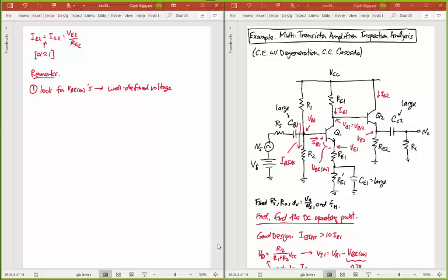And then you want to know how that VBE on, maybe added or subtracted from some other voltage, is dropping across a resistor. And then that determines your current there. So I could say right away, from both these transistor cases here, you can see that the currents are really coming from a voltage drop across RE, and that's usually what you're going to see.